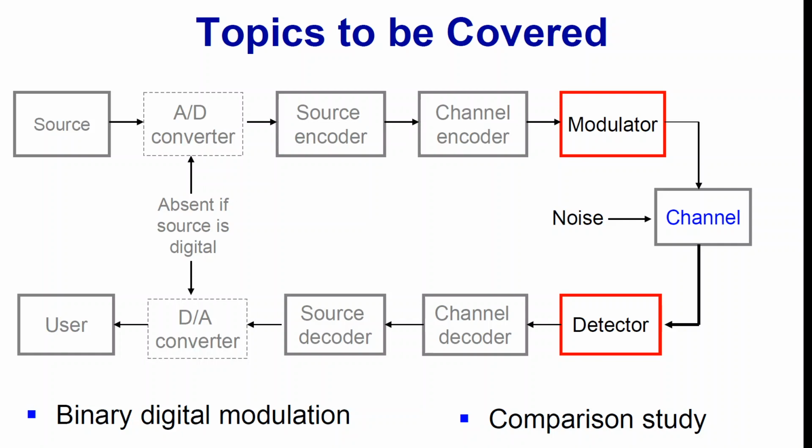It was converted to PAM signals. In the last lectures, we used a binary PAM. So it had only two amplitudes, plus one and minus one. Practically, we can have a lot of amplitudes. So in baseband pulse transmission, these pulses are transmitted directly over a channel.